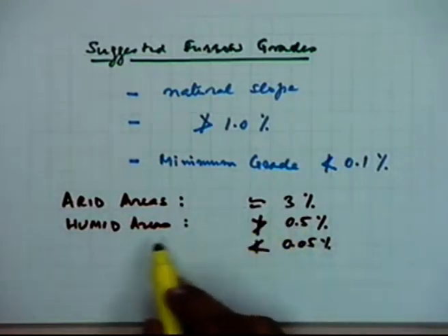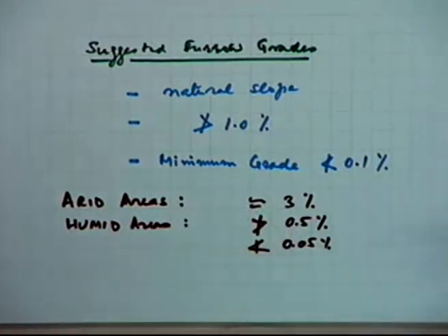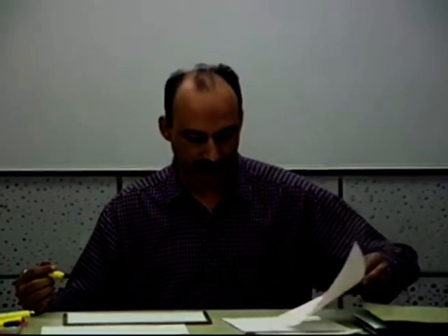Now this becomes the range, which is only a recommendation. If you want to find out the actual slopes, you will have to go in for the actual designs, where you will have to look at the other parameters in combination with these parameters and select them accordingly. That is what the design is all about. You have to ensure that the efficiencies are proper. The efficiencies will be proper if the wastage is less, and erosion and sedimentation are avoided. All those things have to be taken care of.